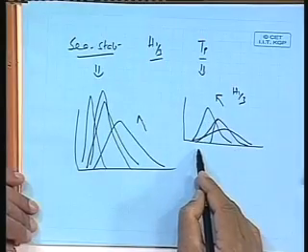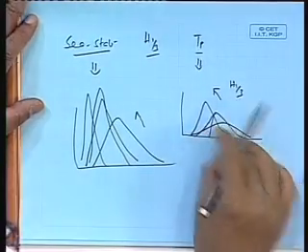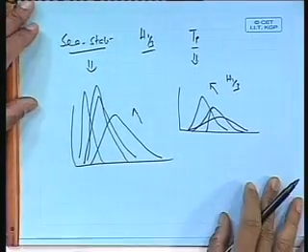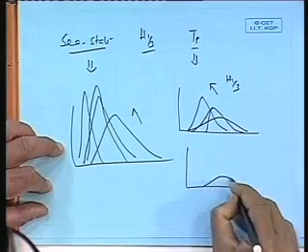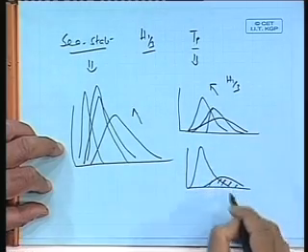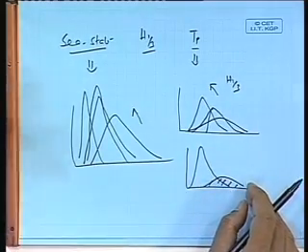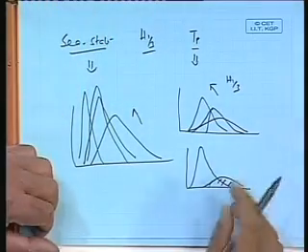You will end up seeing a spectrum having more number of long waves. This I will pick up a little bit in the next class. The energy content will also be more. So you take two things: small height here and very high wave here. The area under that is much smaller because the area is proportional to significant wave height, which is say 2 meter. But there will be more.